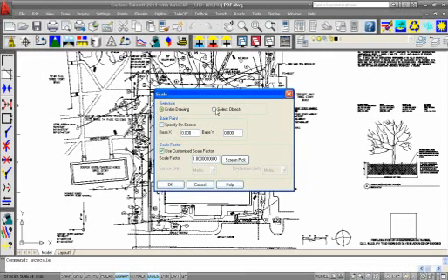So what do you want to scale? The entire drawing or certain objects in the drawing? Just right in this PDF, so we want to scale everything. Use Customize Scale Factor. On this job, that's what we're going to do. But if I uncheck this, you can see some other scaling options that are going to be useful with other drawings. If you're bringing in a CAD file and say it was in inches, it was architectural, and everything you do, you want to be working in US feet.